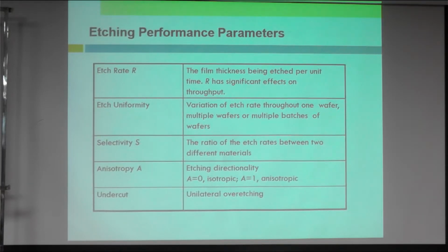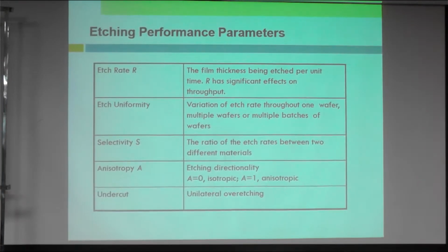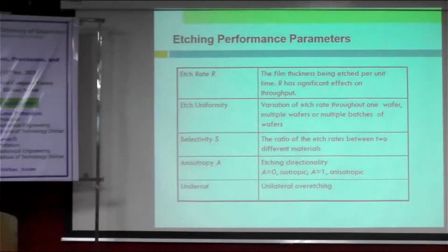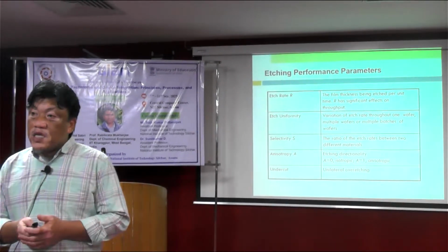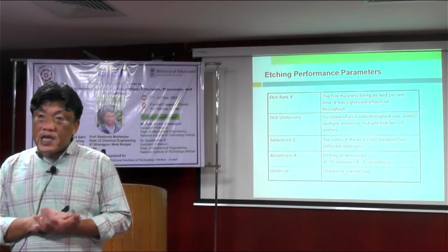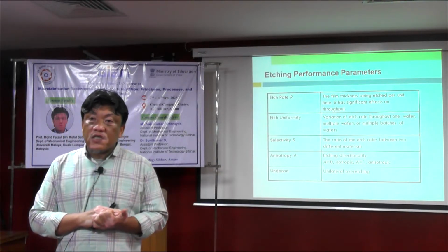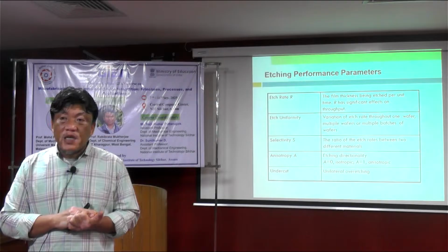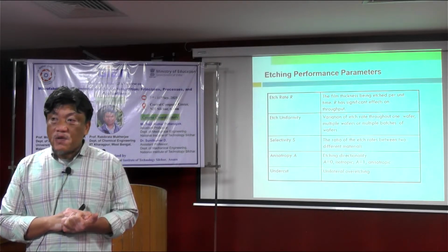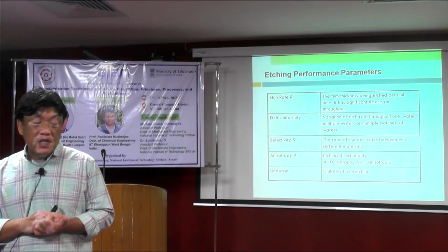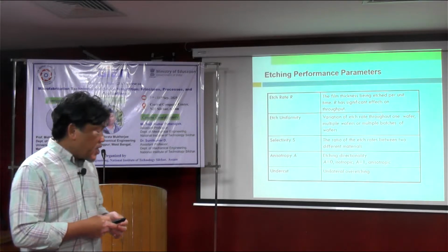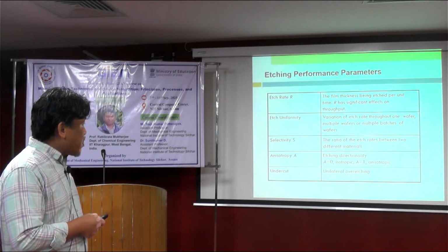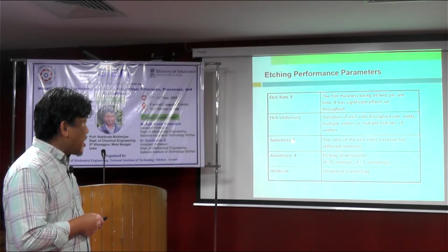You want to remove, for example in the case of a silicon wafer, up to a few micrometers, maybe 15 micrometers, or even 80 or 100 micrometers, while the polymer on top as a mask is maybe only a few microns, maybe 10 microns, for the masking.